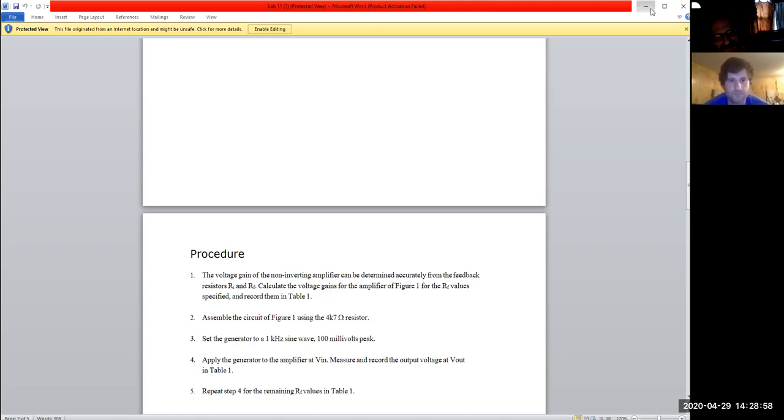But yeah, you got your input, and this is how you can always tell if you're dealing with something really good or not. Look at your input on those power supplies. If you see a fair degree of components where it's getting the AC in to the fuse, then you got a pretty decent one. If it looks really simple, like only maybe one or two capacitors, a diode and a couple of resistors, yeah, that thing's cheesy as hell.